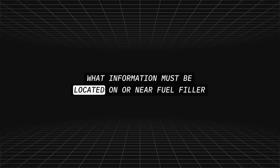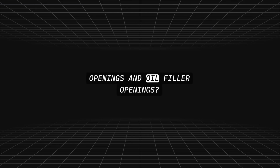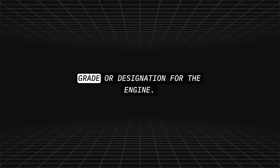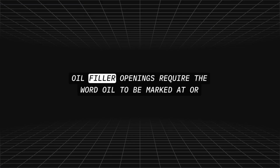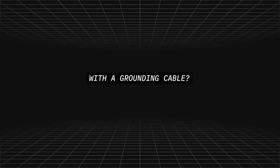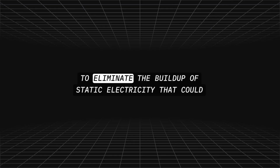What information must be located on or near fuel filler openings and oil filler openings? For fuel filler openings, the word fuel and the minimum fuel grade or designation for the engine. Oil filler openings require the word oil to be marked at or near the filler cap. Why must aircraft and fuel trucks be grounded together with a grounding cable? To eliminate the buildup of static electricity that could result in explosion.